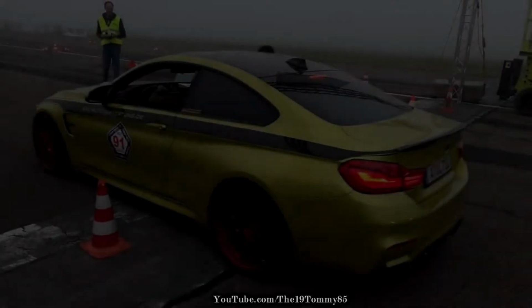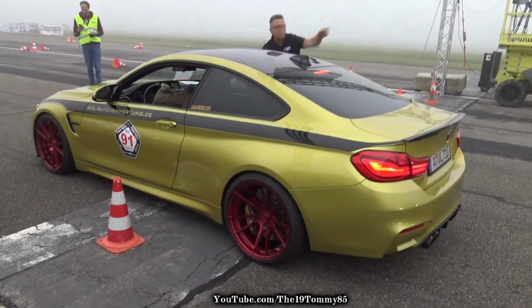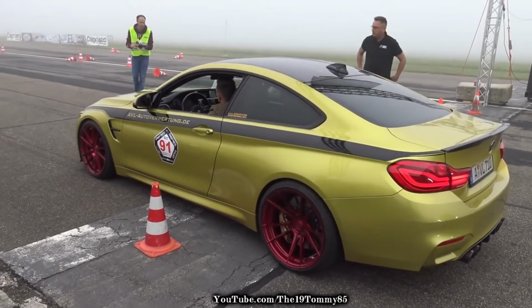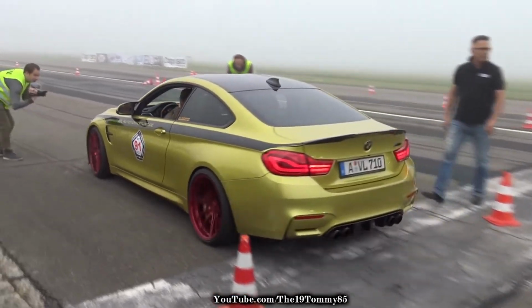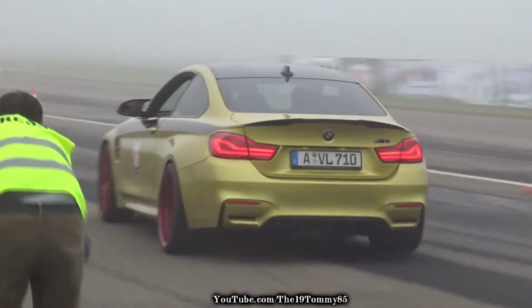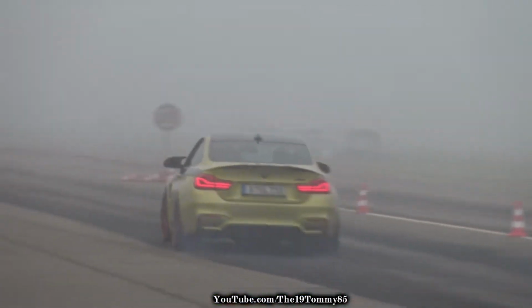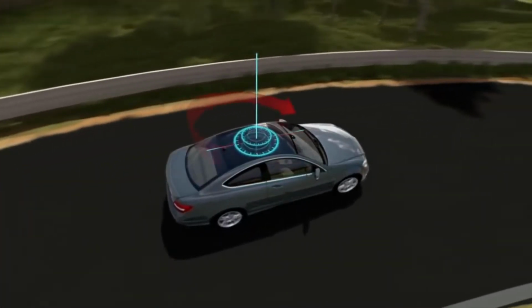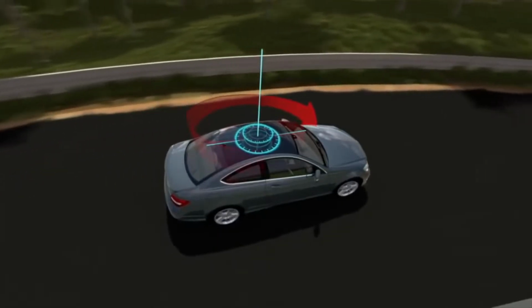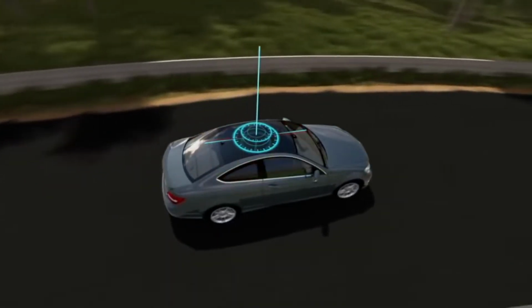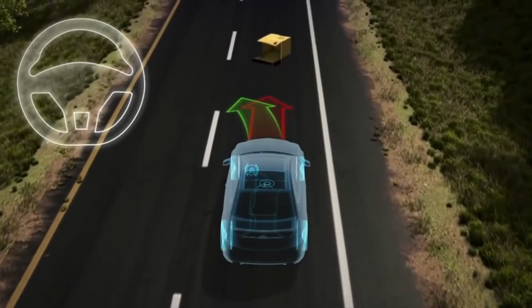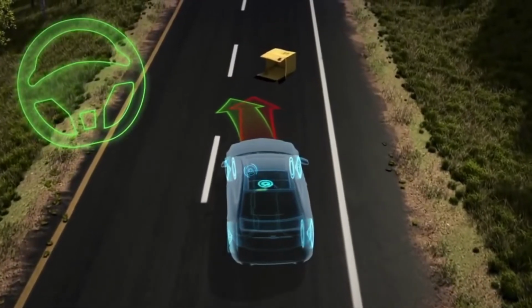Traction is important in every car. Traction is the amount of grip something has on a particular surface. In this case, it's the amount of grip a car tire has on the road. In an ICE car, the traction is controlled through something called ESC, which stands for Electronic Stability Control. Stability control reduces the amount of slippage of a vehicle on roads. In an ICE car, the stability control has a fairly low response. When the stability control kicks in, it cuts the car's power and then feeds the power back in to help the car smoothly get over slippery surfaces.